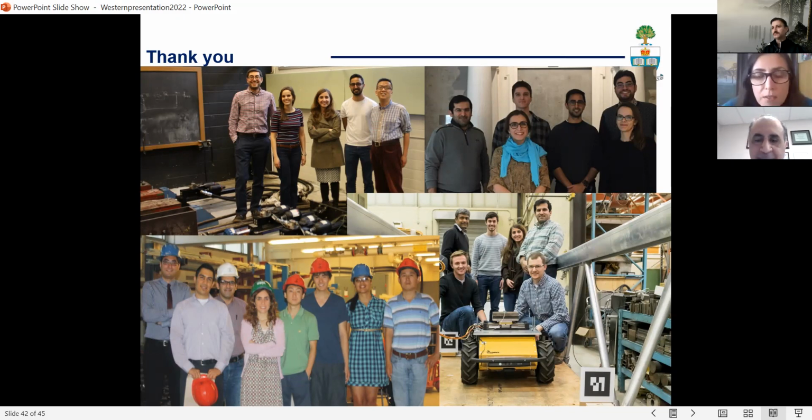So this is a test method to be able to understand the global dynamic response of structural systems, and depending on the interest of the real application problem or the people who are involved in that, there could be very interesting applications also. But one of the limitations is that even in the most advanced laboratories around the world, you have a limited number of actuators. So this kind of determines the number of experimental substructures you can simultaneously test.